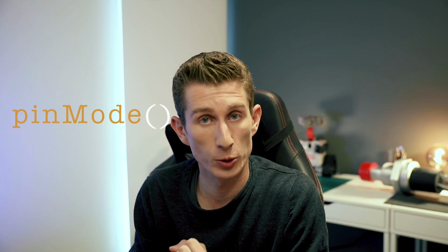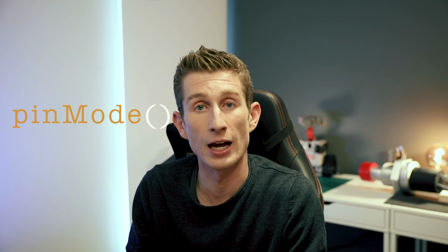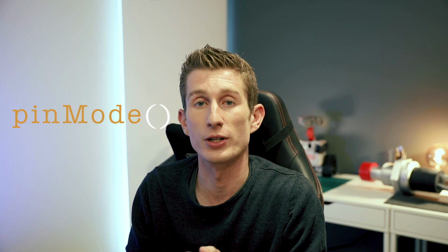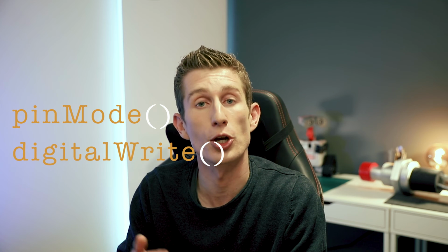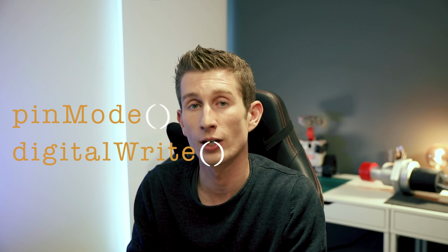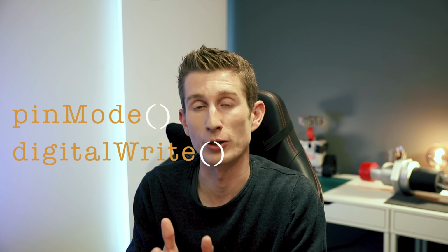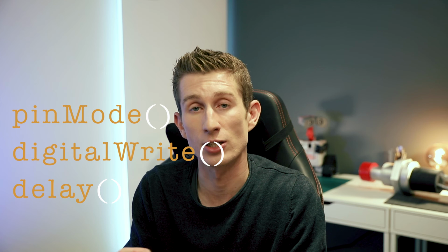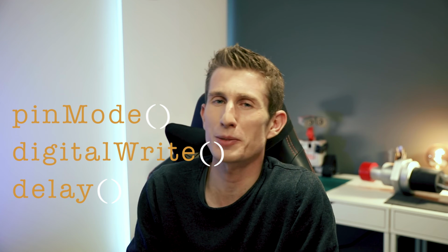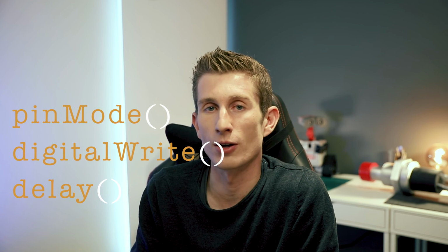We have just gone and learned 3 new functions, especially if it's your first day Arduino coding. We've learned how to assign the job to a pin through pin mode being an output or an input. We've learned how to digitally write to something, turning it on and off using high and low. And we've learned how to send the Arduino on a break and come back later by using delay and assigning it a time in milliseconds. So that's pretty cool. You can be pretty proud of yourself having written your first 3 bits of code, and it only gets cooler from now.